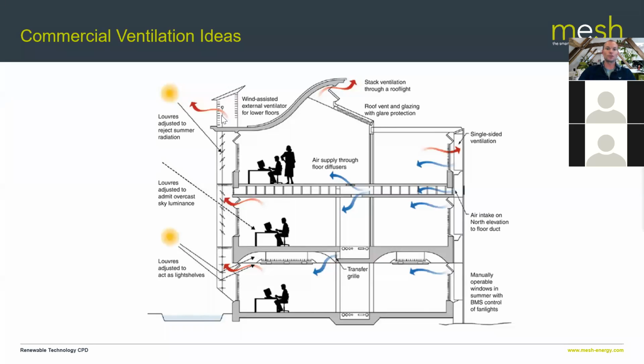But also, again, you've got this kind of chimney feature on the edge of the building, which allows that hot air to rise. But also at higher level, you've got wind that can whip across here and extract that air using the Venturi effect as well. So, there's nothing massively new here. You're just using different features to use these physical properties.